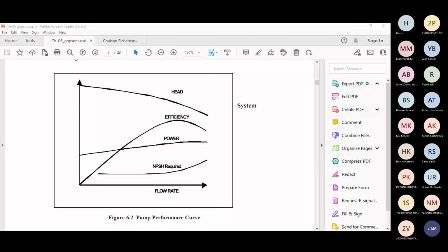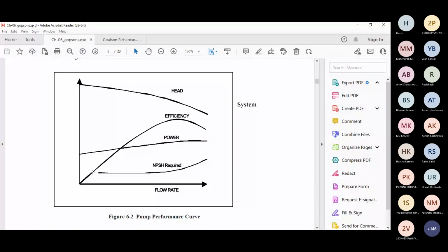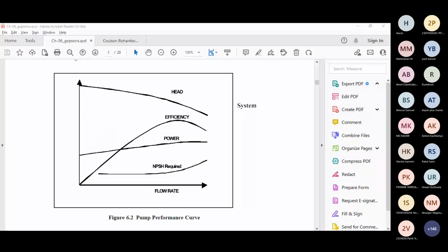See, dynamic pump, when we say dynamic, it is because you are able to get multiple flow rates, right? Suppose at this head you are getting this much flow rate, at this particular head you are getting this much flow rate. So with the centrifugal pump, why is it called dynamic? Because you can have multiple different flow rates, but that is not the case with the PD pump, right? Your PD pump will always be operating at fixed pressure and fixed flow rate. Nowadays, what you can do is adjust the stroke, right? By that you can increase or decrease the flow rate, but it is basically a constant flow rate pump. PD pump cannot be used for different flow rates.